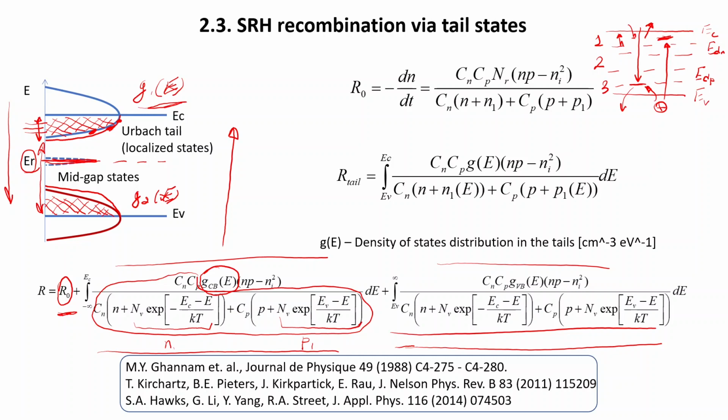It means if an electron or hole is initially trapped, the most favorable and most probable process will be not detrapping but recombination. And that means that it will not have a noticeable impact on the mobilities of charge carriers, because we just don't have any more of these charge carriers. They will vanish, they will recombine. So obviously these energy levels located within region number 2 will have the most important contribution towards the reduction of charge carrier concentration, meaning the net trap-assisted recombination rate.